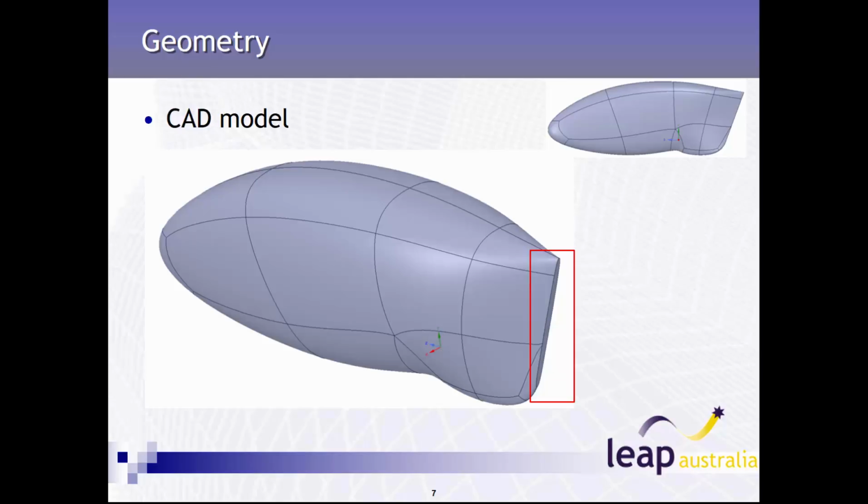Having a look at the CAD model, small adjustments were made. Through running the simulations, the sliver at the end was too thin, requiring small element sizes. In order to make meshing easier, the thickness was increased by taking a larger cut.